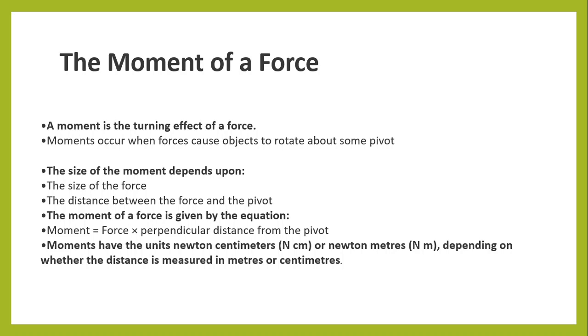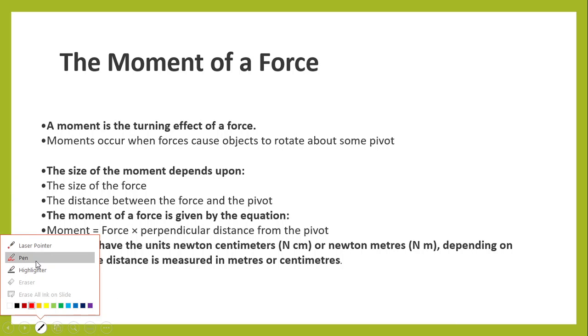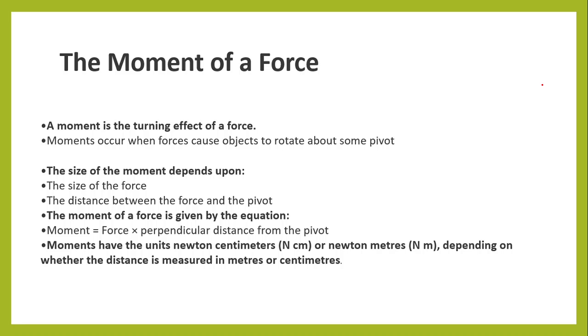The size of a moment. Okay, now we have stated the main equation that is going to govern moments: force multiplied by the perpendicular distance from the pivot gives us the moment. So let's make it easier for ourselves and draw a door.